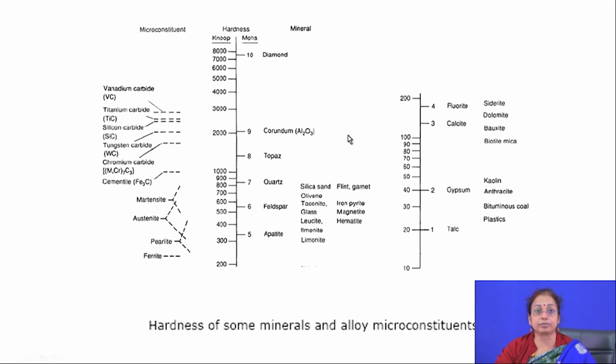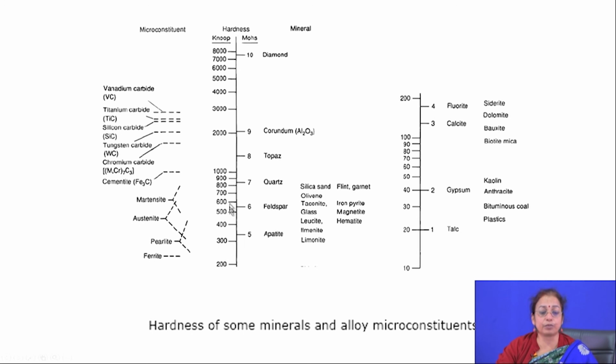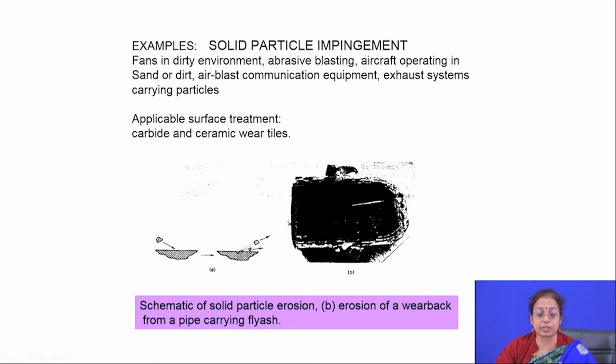If you talk about hardness enhancement, there are different types of compounds and materials available for it. You can directly form those materials on the surface by different treatments, as well as use physical or chemical vapor deposition processes to develop different layers on the surface. If you know your purpose and which material should be applied for which application, you can easily choose a technique and improve the property to a large extent.